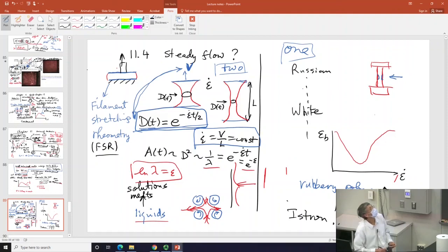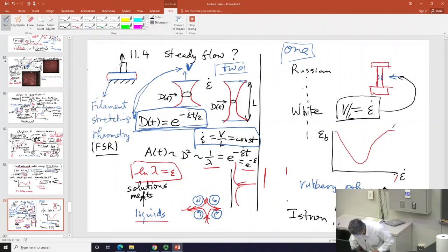I prefer you say it more carefully. So we start with on the right, SER, we start with a constant Hencky rate, and you're trying to maintain the Hencky rate by, of course, having V over L being constant, right? Same thing, but you don't have monitoring, right? You don't monitor anywhere else. At some point, so here's the same game. This condition is the same as when you do shear and close your eyes and hope there's no shear banding. It's the same scenario, yeah?